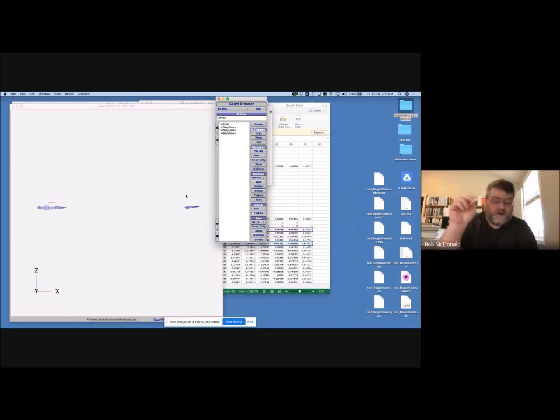Just a 3x5 note card. If I wanted to turn, I'm going to fold it in half so it'll look like a decent airplane. If I wanted a dart to be an airplane, I'd need a wing up here, right? I'd need a wing on top of that CG so that most of my lift was now centered over the CG, and I got my lift vector to counteract my weight vector, and those could cancel out, and I'd get something that could fly and hold itself up.